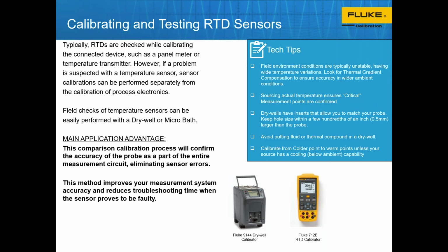That's not recommended practice at all, because no matter how much you clean it, there'll still be something left over. And it's also potentially dangerous because a lot of dry blocks will get you much hotter than the actual fluid can maintain. So if you use water as an example, and our dry block goes to 200 degrees Celsius and water boils at 100, then yeah, you're gonna burn that water off. If you're using oils, even worse scenario, you can get some very, very dangerous temperatures happening with a dry block. So again, don't do that.